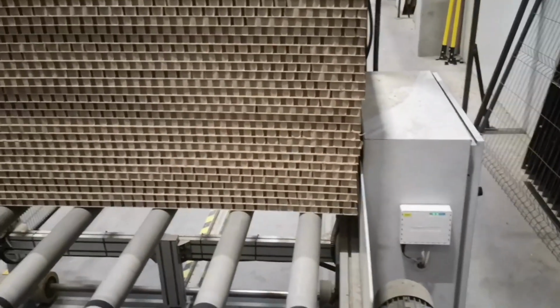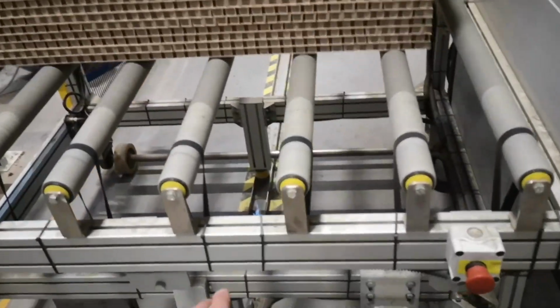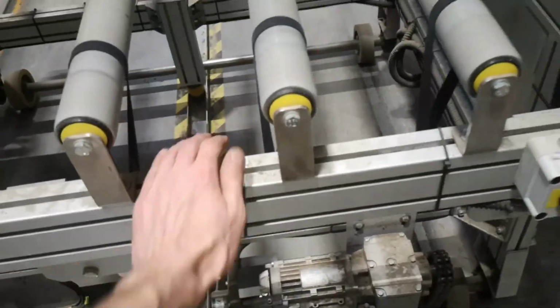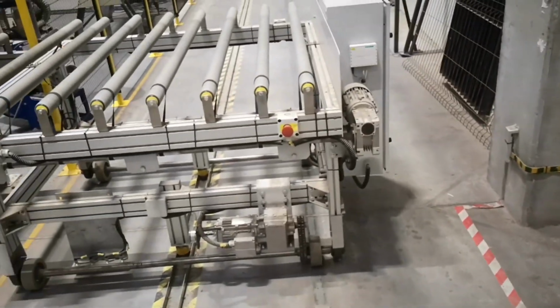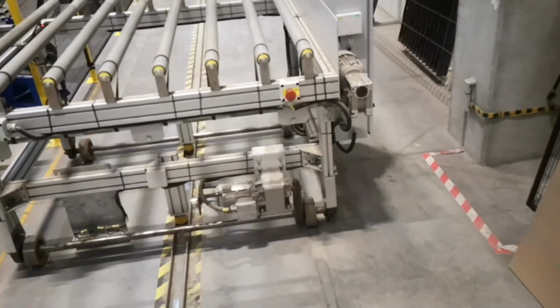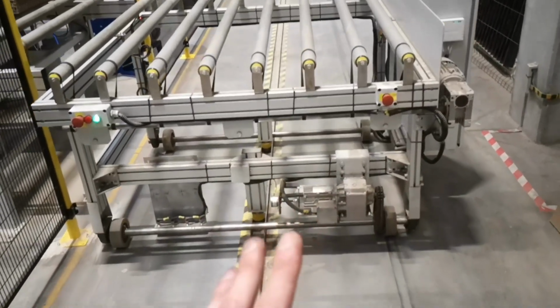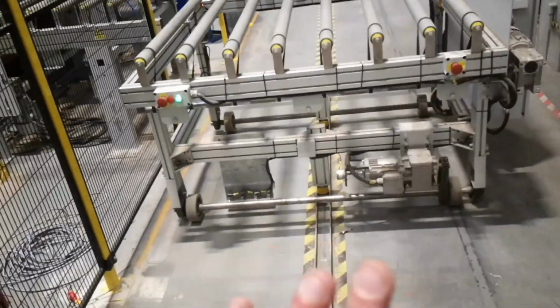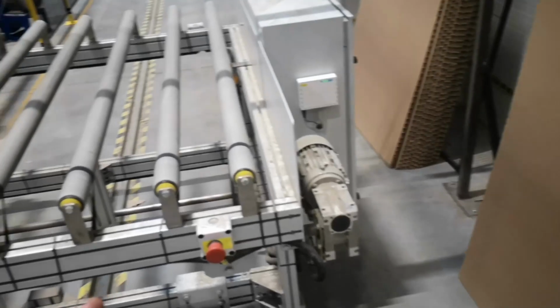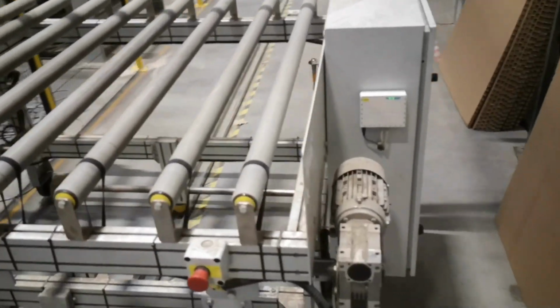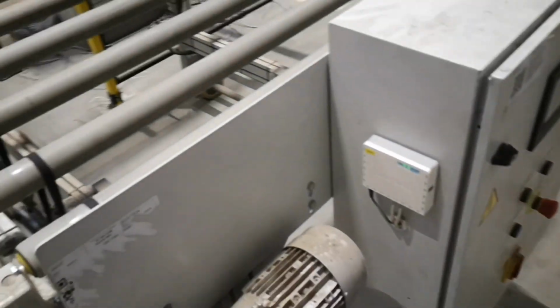For example, in the Delta E or EL series VFD, you can only enable DC brake before running for a preset time and after running for a preset time. But for this VFD, you can give the signal to it, and DC brake will be enabled.